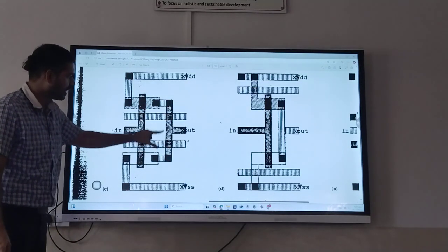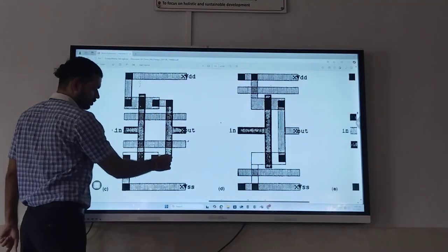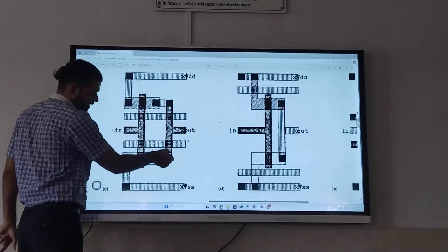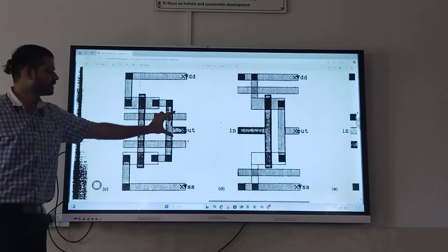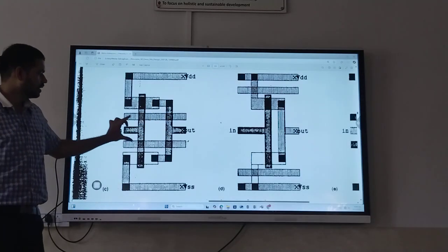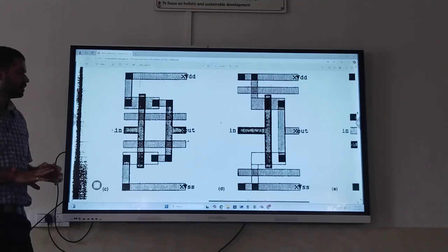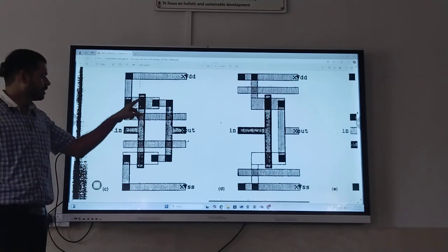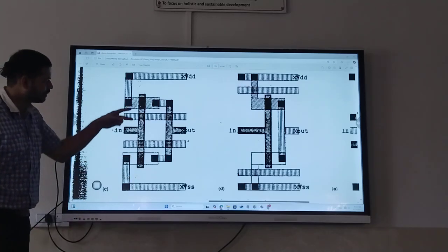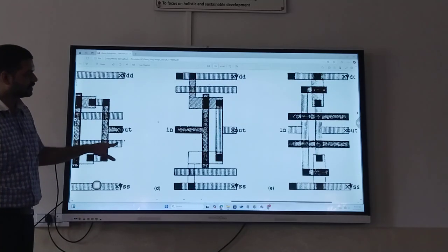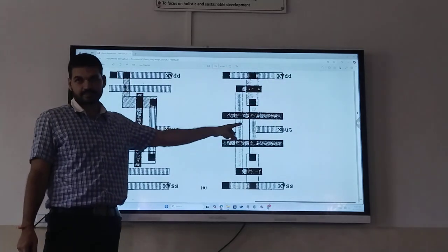So here they are using a via. Metal 1 is converted to metal 2, and via again is converted to metal 1. So here we are passing the two layers of metal 1 through the layout of the inverter. If we want to pass some poly through it, then it may differ. See here, this case.